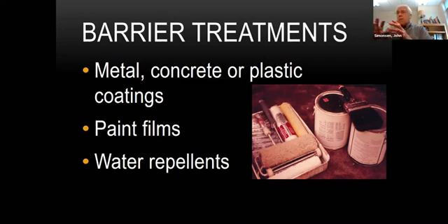So if you wrap the utility pole in plastic and get the wrap more than 18 inches above ground, it doesn't eliminate the need for a preservative, but it will reduce the need for a preservative retention. So you can use a lower retention, with less leaching, more environmentally friendly.